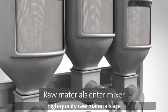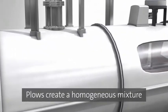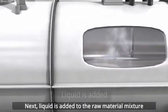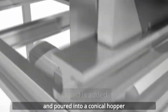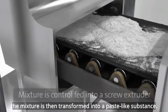To begin the extrusion process, high-quality raw materials are blended to create a homogeneous mixture. Next, liquid is added to the raw material mixture or poured into a conical hopper. The mixture is then transformed into a paste-like substance.